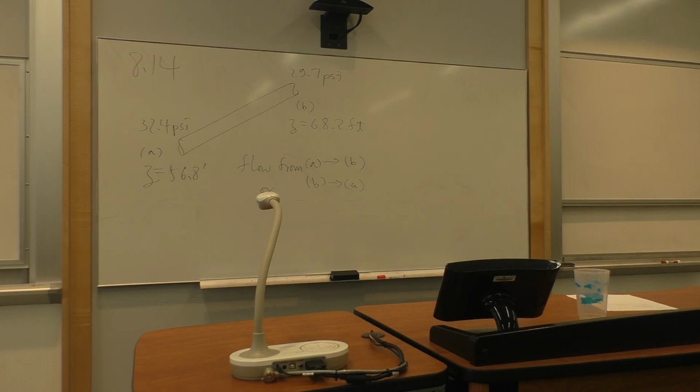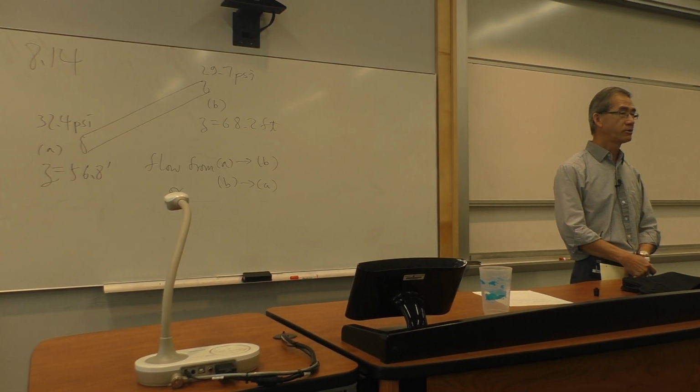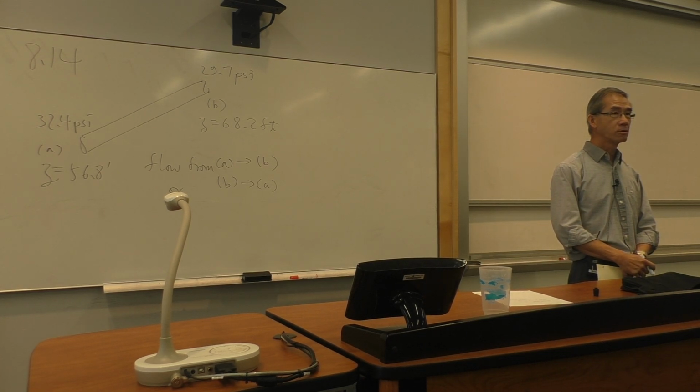Bernoulli. Oh, very good, Bernoulli. There's nothing wrong with Bernoulli. Do you want to use Bernoulli? Sure. What do you assume when you use Bernoulli? What do you have to account for to use Bernoulli? Inviscid flow? Do you want to assume inviscid flow now? No. Moving forward, we grow older by a month. You're more sophisticated. You are now dealing with viscous flow in chapter 8. Do you still want to use Bernoulli?